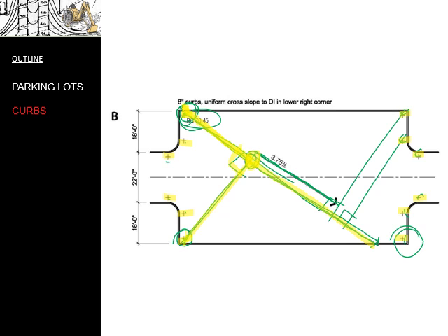You will discover that you're going to have to get a little creative in some of these because you might discover that the line doesn't go as far as you might want. So you're going to extend that line on out to make sure that you can get all of these spot elevations calculated using that baseline to begin with.